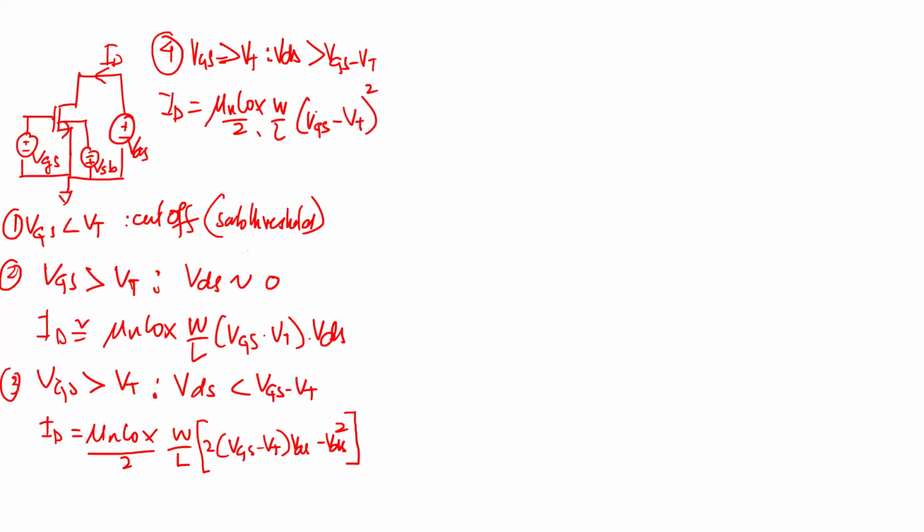Okay, constant current, but there is actually a modulation, especially as you've seen yesterday in your simulation, when you took the channel length to be 0.15, the variation was actually quite a bit with VDS, right? So in reality, you have this lambda term, which varies with VDS. If your length is small, then the lambda will be large. That lambda is inversely proportional to length and directly proportional to current. So if you want a large R out or RDS, you want a longer length and smaller current. That's what gives you a larger R out.